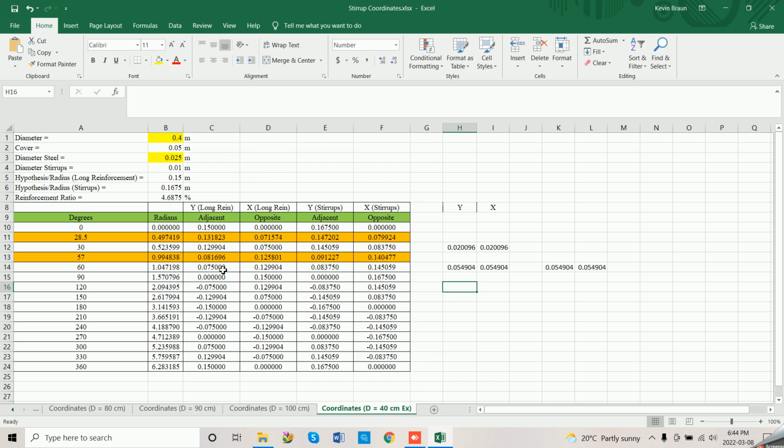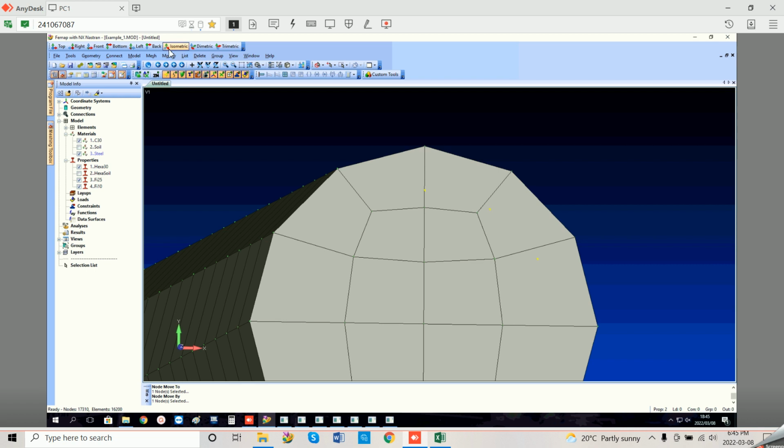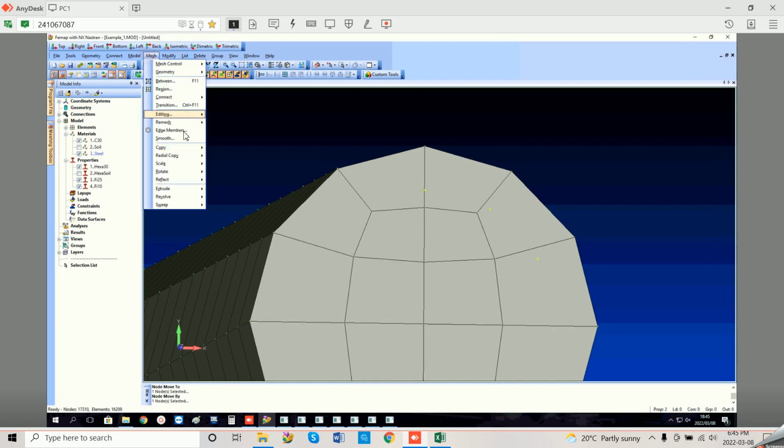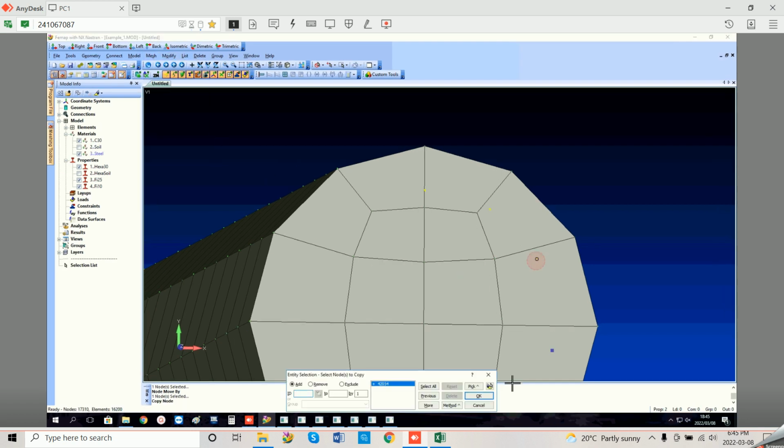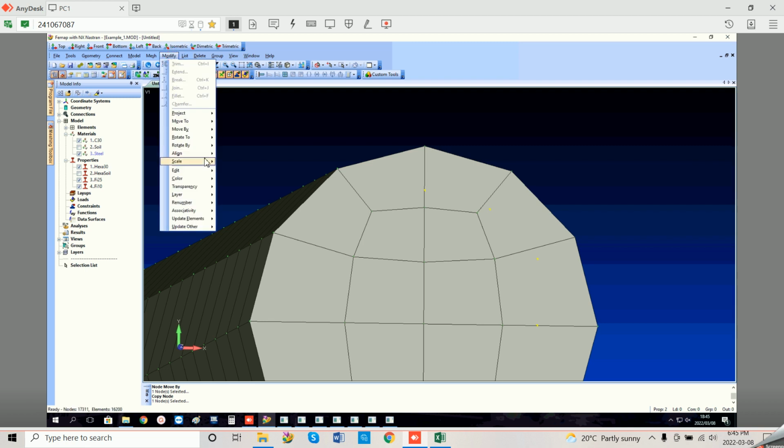Sorry, I'm just checking. Yeah, so you're going to be moving your y node 0.7 down, and then your x node will be that difference. Okay, so let's do that quickly. Mesh, copy node, take that node. We go negative y, and this was 0.075. Click OK. Yes, it makes sense because it's on that line.